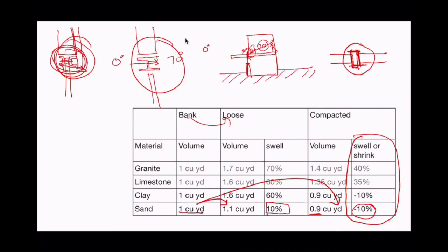So in the mental model of the really, really tight, high performance, low energy building, we do worry about bolts going through it. We definitely do. But frankly, we worry about those more from an air leakage point of view than from a thermal bridging one, though we worry about them for both. And we might eliminate the balcony altogether. But from the point of view of just a good, high efficiency, low energy building, we don't, because it's so much better than the alternative. We're not worried about a little bit of bridging going across with the bolts.